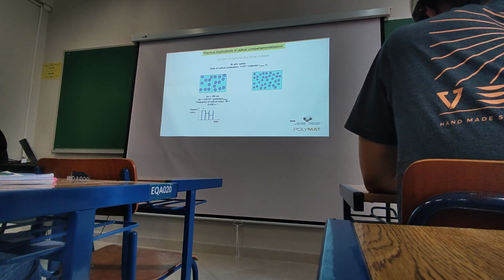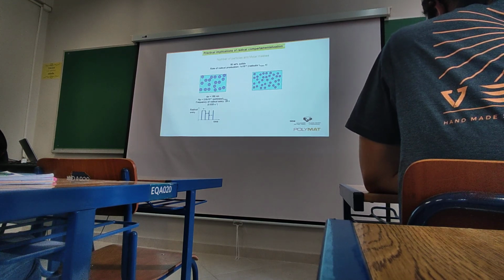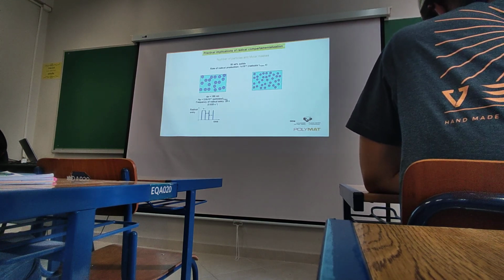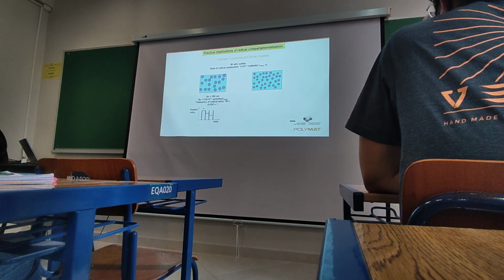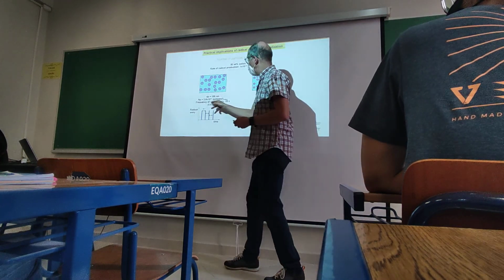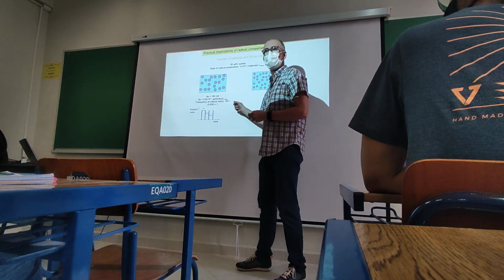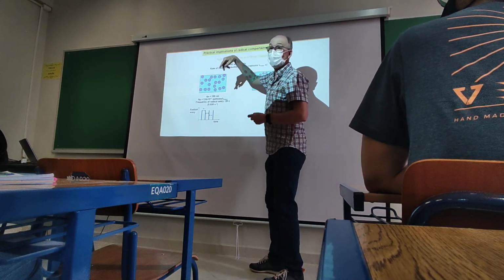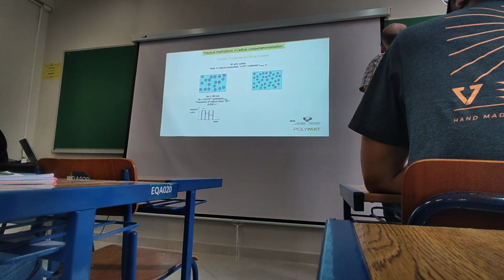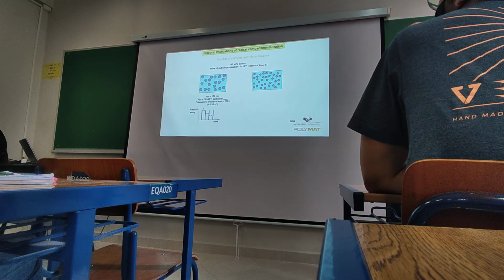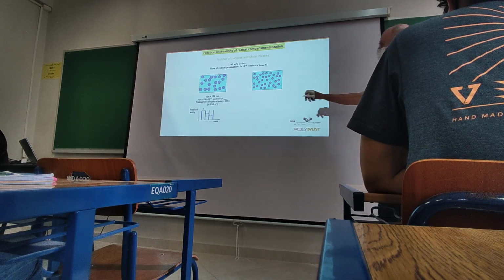2.8 to the power of 17 particles per liter when the particle size is 150 nanometers. So the frequency of radical entry, which will be the rate of the radical generation, this Ri, divided by the number of particles, this is the frequency that you have here.